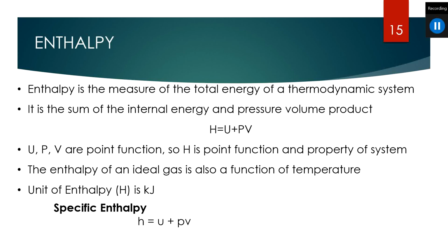You have already studied enthalpy. What is enthalpy? Enthalpy is a measure of the total energy of a thermodynamic system. It is the sum of the internal energy and the pressure-volume product. Enthalpy is represented as H and is equal to internal energy U plus P into V, where U, P, and V are point functions. So H is also a point function and a property of the system.